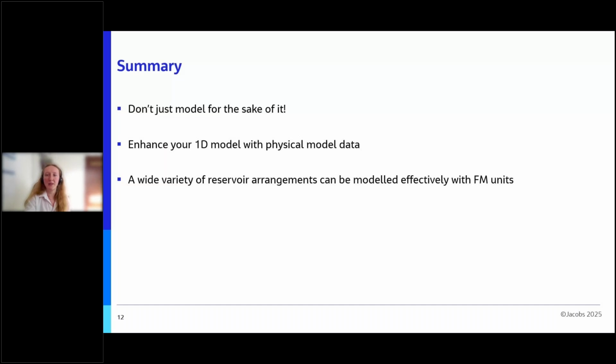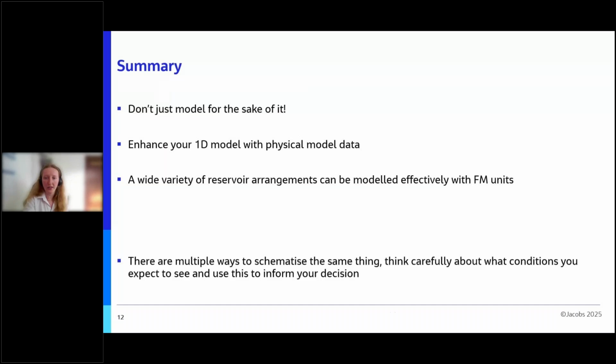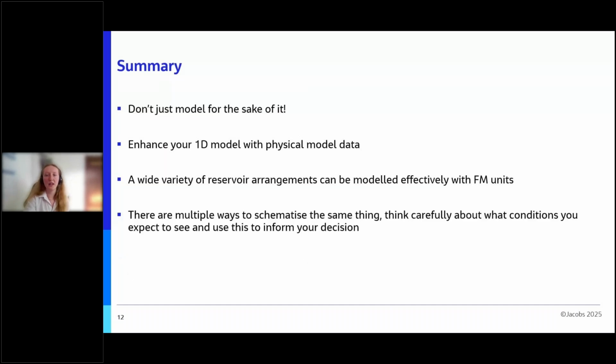Flood Modeler is being completely rebuilt for version 8, which is due to be released later in the year. This will include enhanced, fully integrated units, such as the revamping of the weir unit. And I'm hoping these newly developed structure units will help deal with some of these non-standard reservoir structures. And then my final takeaway point from this webinar is that there are multiple ways to schematize the same thing, but just think carefully about what conditions you expect to see and use this to inform your decision.